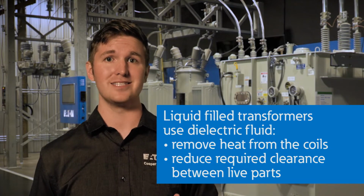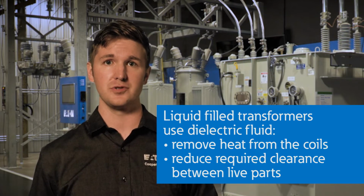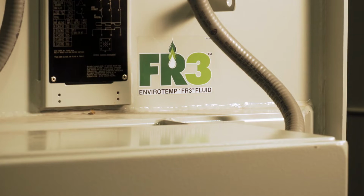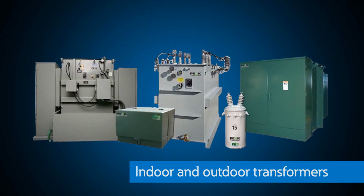Liquid-filled transformers utilize dielectric fluid both to remove heat from the coils through convection and to reduce the clearances between live parts. Modern liquid-filled distribution transformers are filled with biodegradable natural ester fluid like FR3. FR3 and other high fire point fluids also meet code requirements dictated by organizations like FM Global and Underwriters Laboratories, or UL. The resistance to fire drastically increases the safety of the liquid-filled transformer designs, allowing users to take advantage of the performance benefits of a liquid-filled transformer for indoor and outdoor applications.